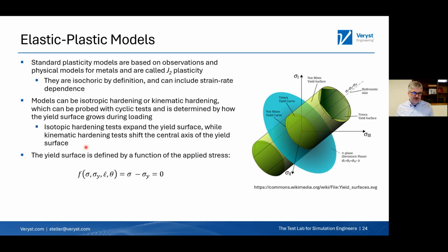If you start to talk about a Neo-Hookean model, again, you need a bulk modulus and a shear modulus. You can get those, but then you don't have a lot of other control. As you increase complexity, you have 10, 12, 15 or more parameters. How do you find each one of those parameters? The way we do it is essentially we do a single element finite element simulation with a candidate material. Then we compare that to our test data, and we do some nonlinear optimization on the material parameters, and we run that hundreds to thousands of times.